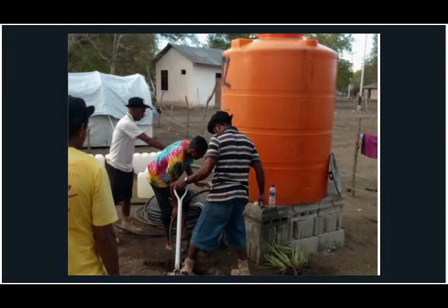And so this is a much higher level of analysis and much higher skill level, when we include people such as hydrogeologists who can model the groundwater and model what the safe yield of an aquifer is, how much water is allowed to be extracted from the aquifer before there become problems with the aquifer, such as saline intrusion. So that's when salt can come into the aquifer and then it can destroy the aquifer, and it does not become fresh anymore. So that's a much higher level.